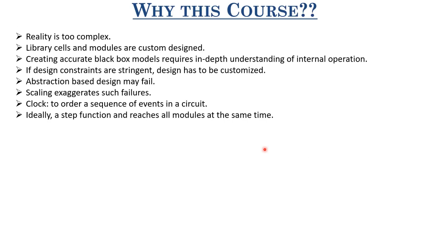The interconnect line has to traverse a certain distance, and within that distance there would be a certain resistance offered by these interconnects. Because of that, there would be an IR drop across that interconnect. And as such, as you go from one module to another, there's a drop in the supply voltage that they see.